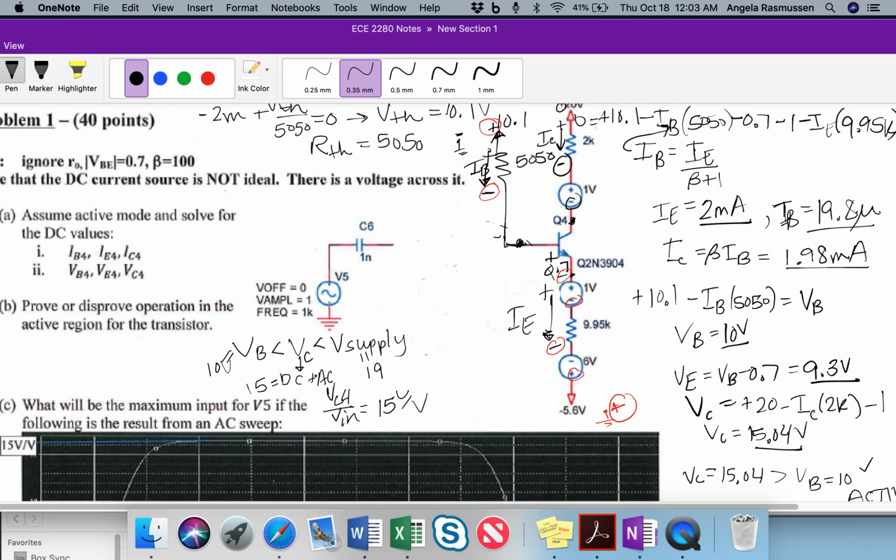So the AC portion that could be added here: it would be to take off 5 volts to get to VB, and add on 4 volts to get to the supply. The lower value out of that comparison is 4 volts, and we're going to limit the AC portion to the smaller value, because the smaller value is more limiting.